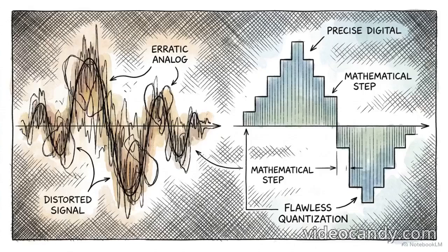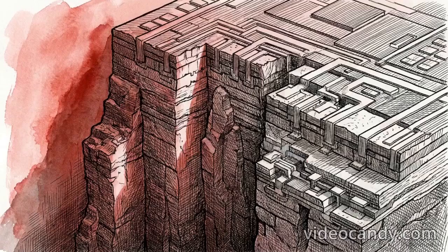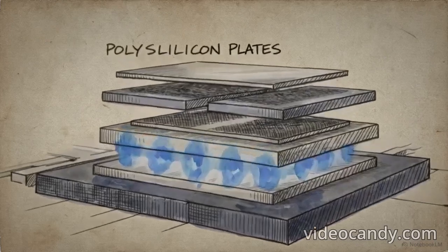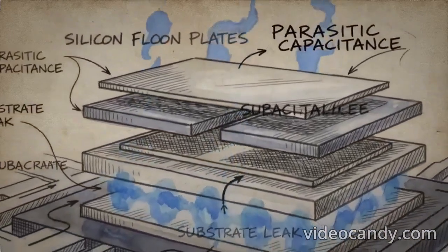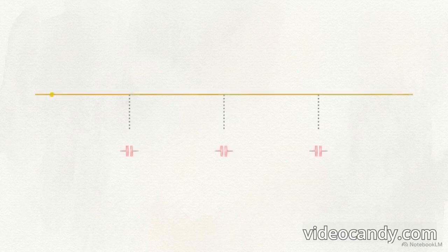The exact height of that step is determined strictly by the ratio of C1 to C2 and the previous input voltage. That staircase waveform is the highly precise, discrete time equivalent of a continuous mathematical integral, executed entirely in hardware and fully immune to the matching errors of physical resistors.